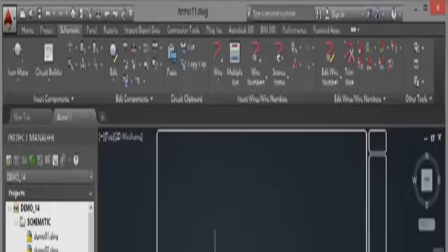When you place a three-phase ladder, it is subtly different. So if I click like that and then just drag downwards, that's how it places the three-phase ladder. It just keeps going unless I've specified the number of rungs needed. So if I click there like that, there's my three-phase ladder. So if I zoom in on that now, you can see 1000, 1001, 1002, 1003.